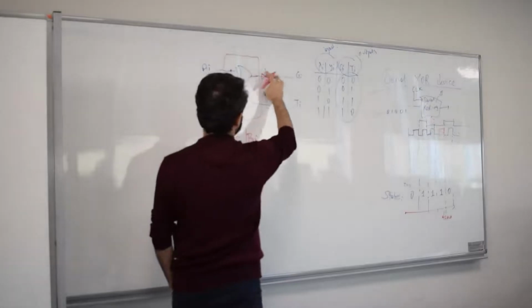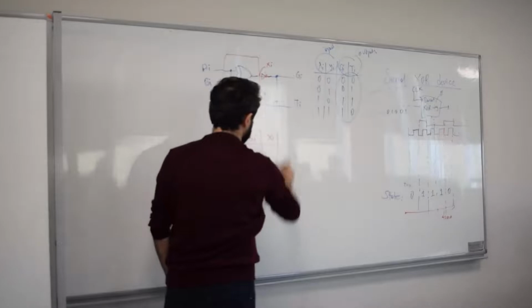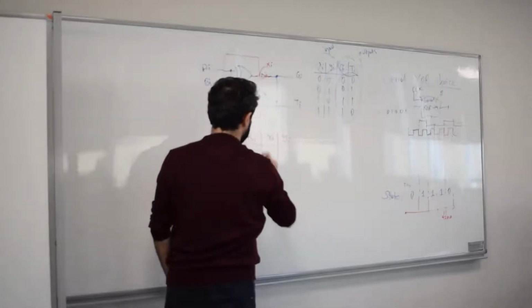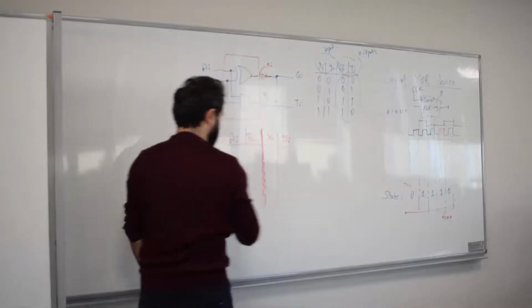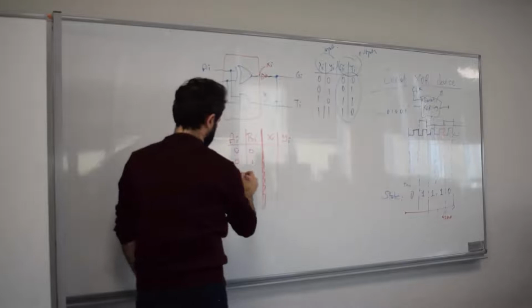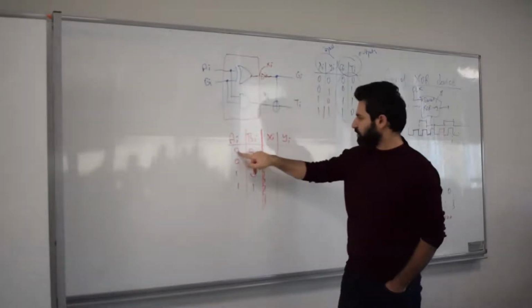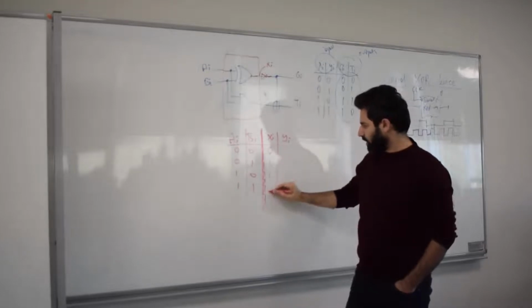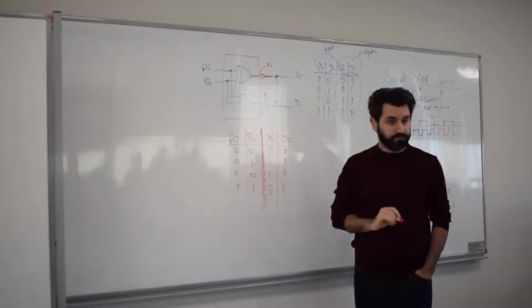Let's suppose that XI is defined to be here, which I'm going to change later on, by the way. This is just for any practical cases. I want you to remember the half adder: 0, 0, 0, 1, 1, 0, 1, 1. So what is XI, the XOR gate? It's going to XOR these: 0, 1, 1, 0. What is YI? The AND gate: 0, 0, 0, 1.